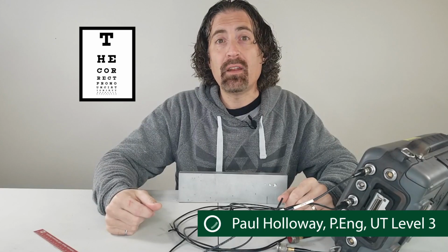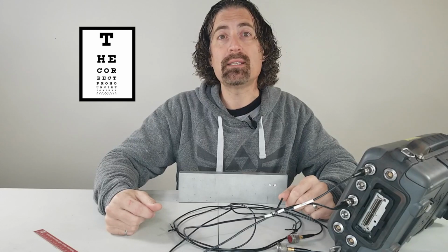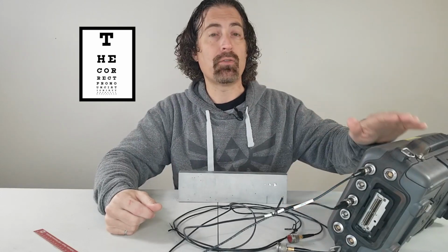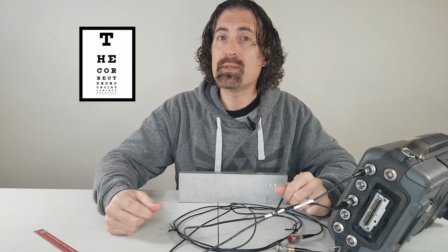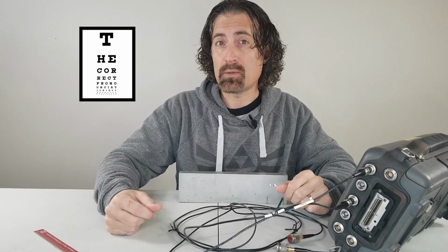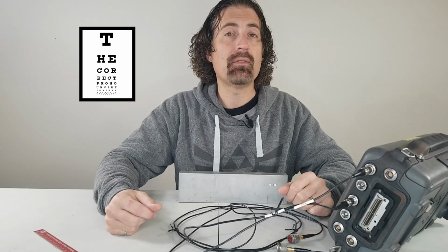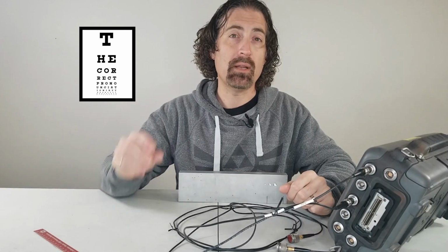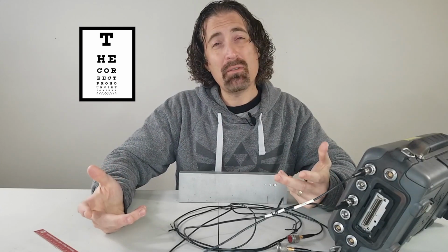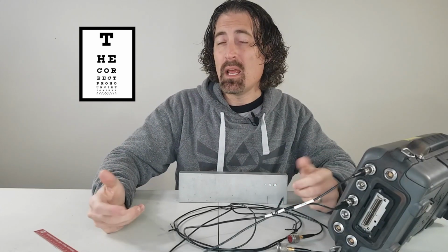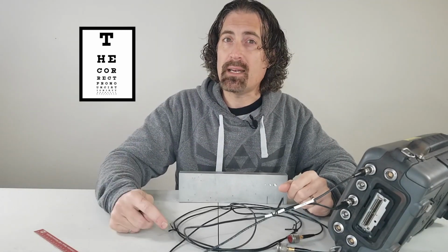Resolution and sensitivity are two terms that come up a lot in ultrasonic testing. Now, resolution is the ability of the system, which is your flaw detector and your probe, to tell the difference between or resolve multiple closely spaced reflectors, whereas sensitivity is the ability of the system to detect really tiny reflectors. It can be a little bit difficult to try to envision how this all works, but it's not so difficult if we use digital photography as an analogy.